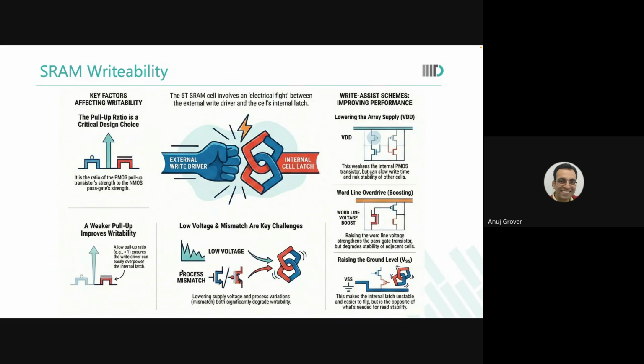If you do it much after this point, then you have wasted so much time. That is, performance has gone bad. So you want to bring this lowering as close to bit line touching 0 as possible. It's not simple. It requires design creativity, but you have to do it, and we'll do it. This is a part of write driver design. I don't think we are going to touch that today, but we may.